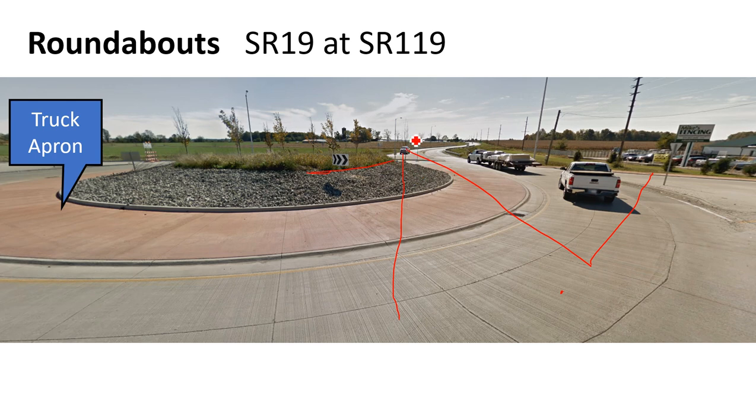And again, this is an intersection sight distance piece, and so that's 3.5 foot tall object and a 3.5 foot tall eye through there. Here's this mountable curb out here. We've got inlets in the center, so this one's actually they've sloped this 2 directions, which is a little odd, but it's such a wide roadway. That's maybe one of the reasons. This is your high point here, and you have water sloping in, so they have inlets on the inside. They also have inlets on the outside in spots, and sometimes just curb turnouts, letting the water into the ditch through there. So that's an example of design.